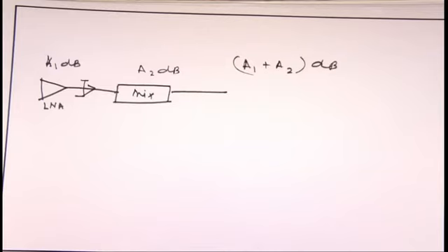One is that the gain just by adding would not always be the same. And second is that you should have a mixer in your plan when you are designing an LNA. Then you will get a much better picture of your LNA performance as well as the mixer. If you are not able to do the mixer design, you should have a mixer outside to characterize the LNA.